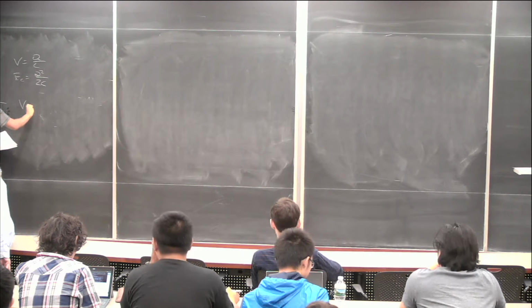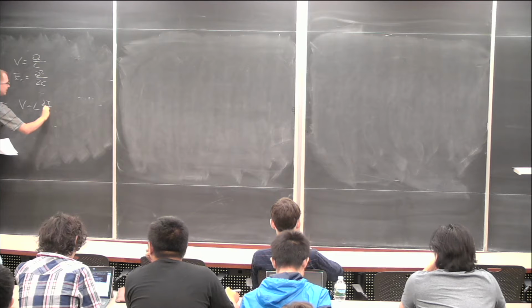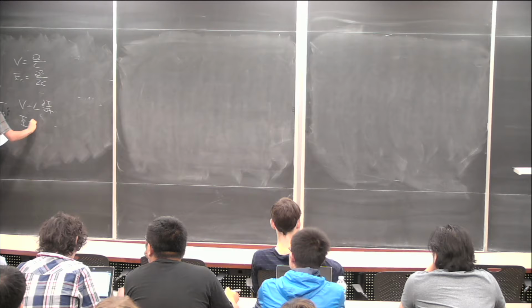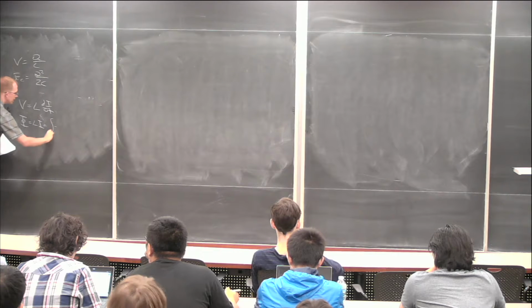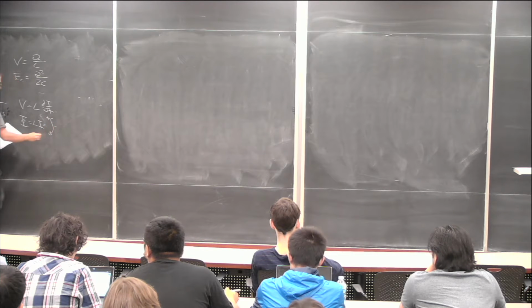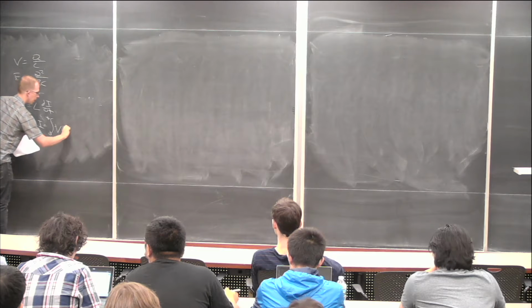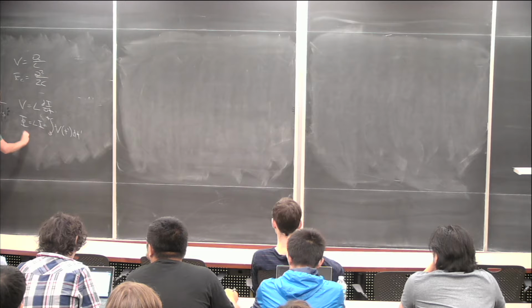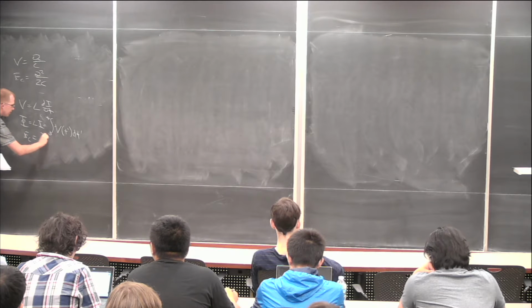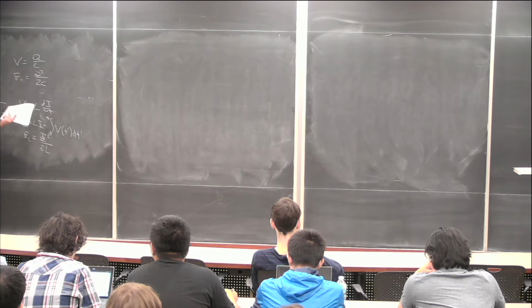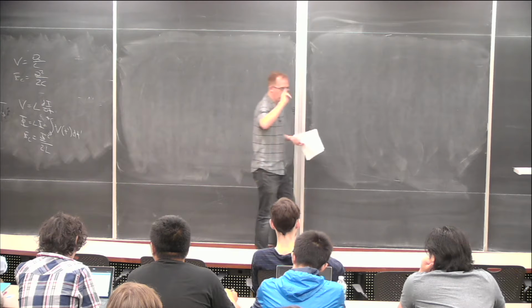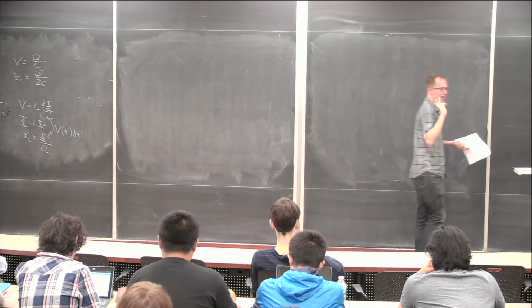And the voltage on an inductor is L di/dt, which gives us a flux, which is L times I, which is the integral of the voltage over all time. And we can define an inductive energy, which is this flux squared over 2L. Very good. Simple components.